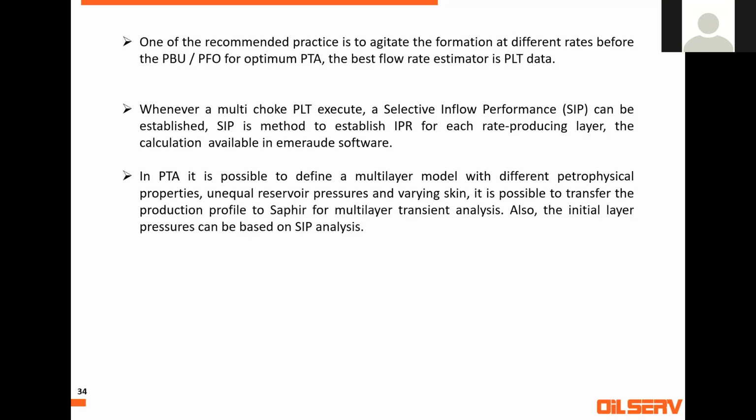This can take us to an extra step. Now you have the rate per each zone. Now you have the P initial per each zone. So you can make a PTA analysis with a multi-layer model, because you can enter each layer flow rate. You can enter each layer P initial. Going further,